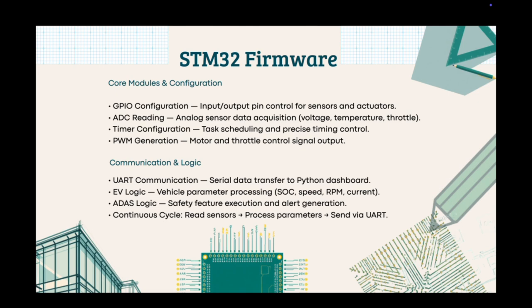After reading the data, the firmware processes important EV parameters like battery percentage, speed, RPM, and current consumption. It also executes the ADAS logic to detect conditions such as overspeed and collision risk. Finally, all the processed data is transmitted to the Python dashboard through UART communication, and this process repeats continuously in real time.